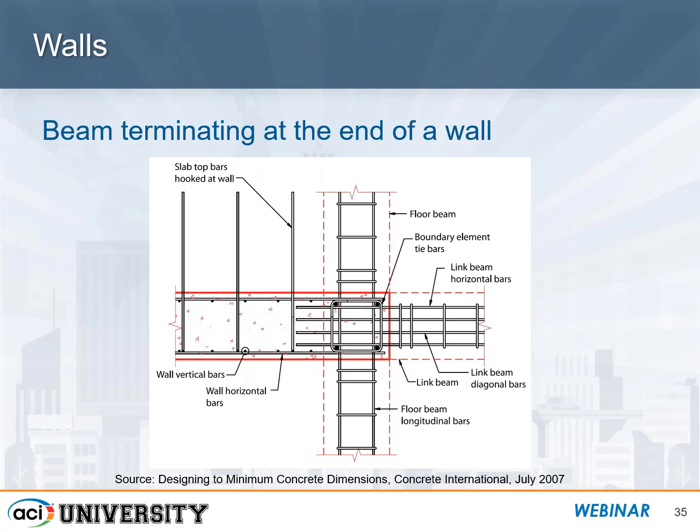So that's one consideration. The other consideration is, what if we have some beams that are framing into the end of the wall? And those beams may be carrying just gravity load or whatever the case may be. Now you're talking about having longitudinal bars coming through, and it could be in either direction. So that's something to keep in mind when you're talking about providing a certain thickness to avoid any type of congestion here.